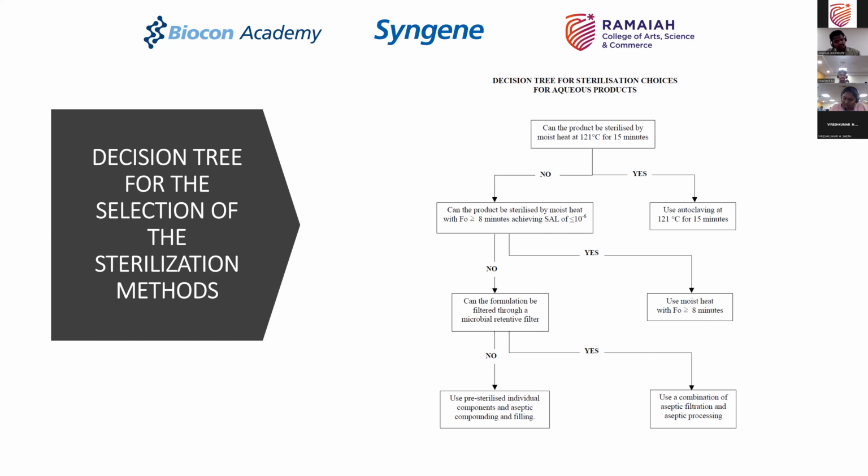As I said, can I use moist heat to sterilize it at 121 degrees centigrade? If the answer is yes, go ahead and use only terminal sterilization. Now, the answer could be that in 15 minutes it does not get sterilized. With an F0 value of greater than or equal to 8 and achieving a sterility assurance level of 10 to the power of minus 6, can you still achieve the sterilization? The answer could be yes or no.